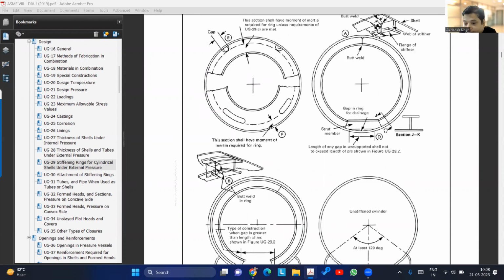Right now, I'm designing one tank which has 12 compartments, and there are 12 baffles dividing two compartments. The baffles are 10% less than ID. So my question is whether we need to provide external stiffeners or whether code allows us to eliminate the external stiffener. Why are you getting confused with baffles and support ring?